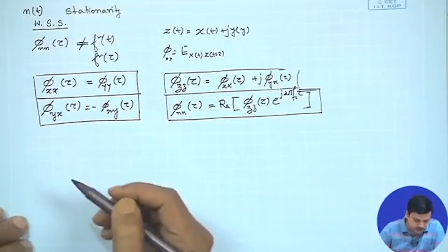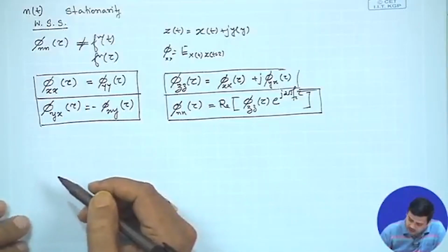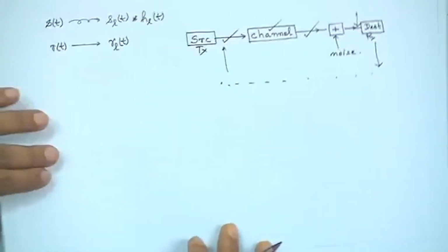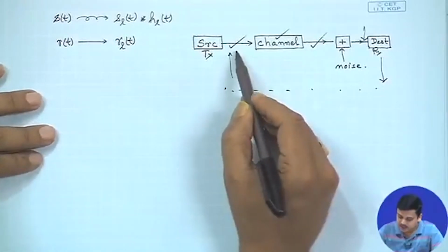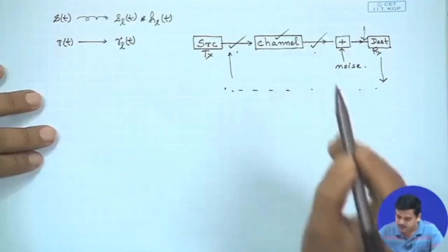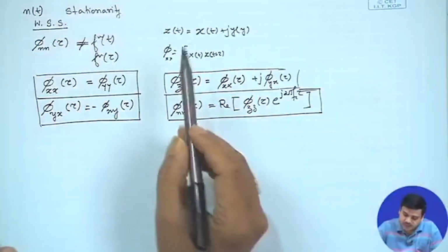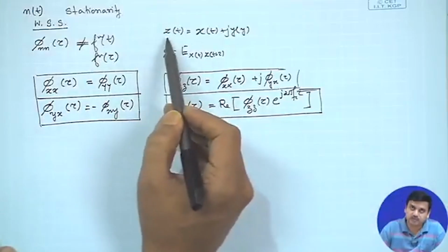These are some of the relationships we established in the previous lecture, and this would help us. Now, we said that this is deterministic, but since these things are typically the outcome of a stochastic process, there is not much sense in actually taking the Fourier transform of these z(t) or n(t). Rather, what we would be interested in are correlation properties and the power spectral densities, which are duals of each other in terms of Fourier transform.